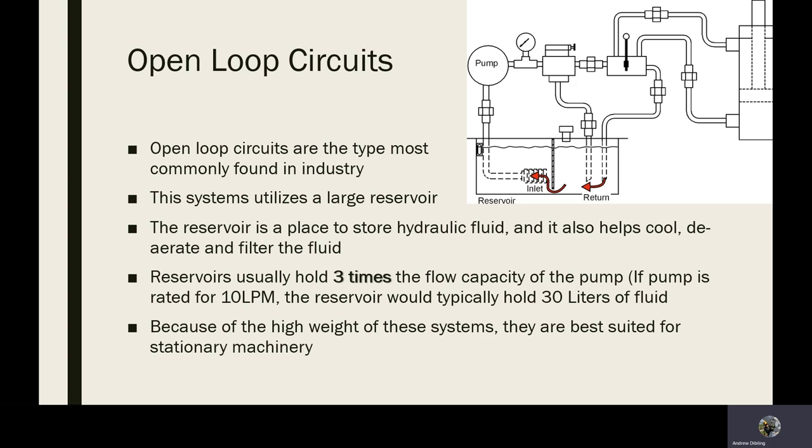And again, the reservoir is there as a cooling chamber for the fluid. It may have a cooling fan attached to it with a little pump inside that will actually circulate the fluid up to a heat exchanger, which will then dump heat out of the fluid if it's not cooling down fast enough. You can also have heaters in reservoirs if the fluid is experiencing cold ambient conditions like -35, -40 degrees. Fluid sitting around in the bottom of containers will get quite viscous, and it may not be circulating the entire volume of the fluid.